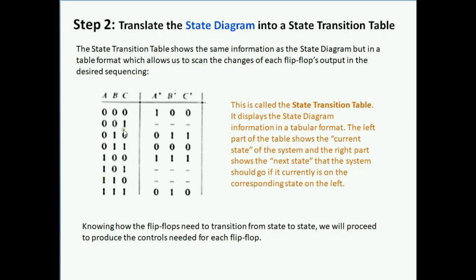These are states for which we do not care what the output of the flip-flops will be. So they are, in fact, don't cares. These outputs can be designated to be anything you like that suits you or makes your life easier when it comes to optimizing the design. Why? Because they're never going to appear. So if they're never going to appear, you might as well define the next state to be anything you want, exactly as it suits the optimization of the design.